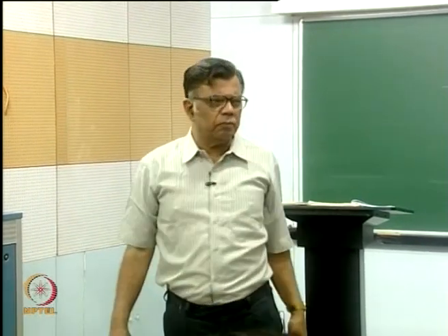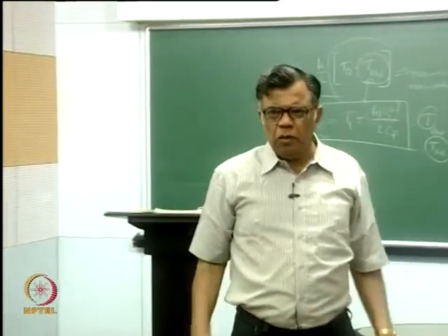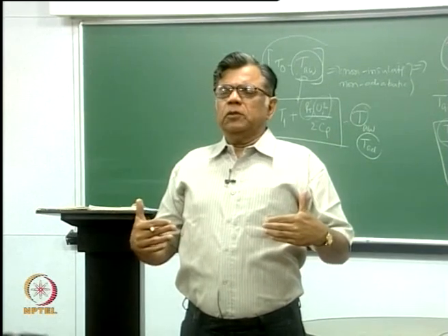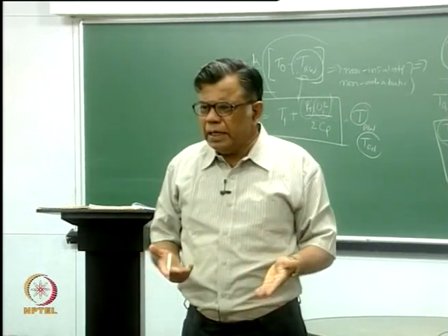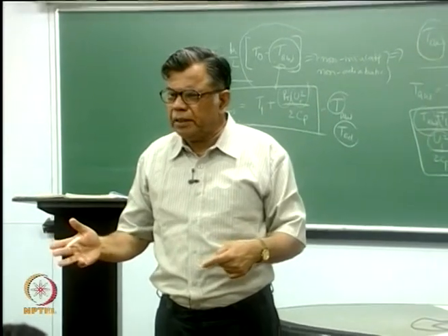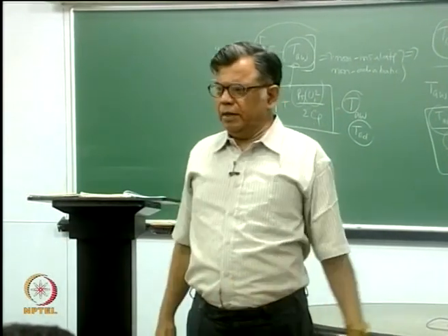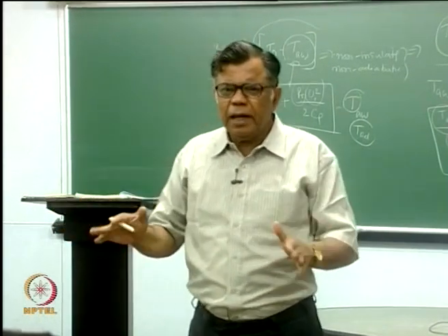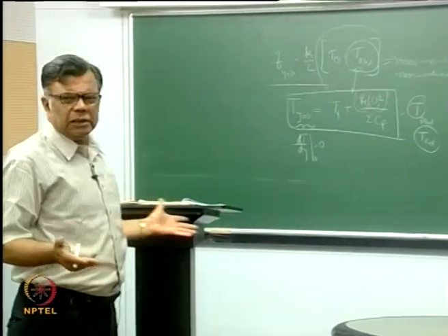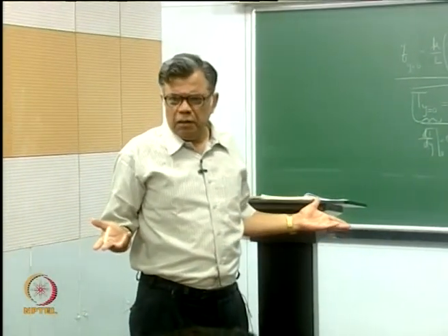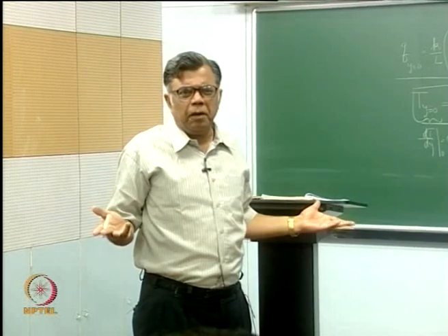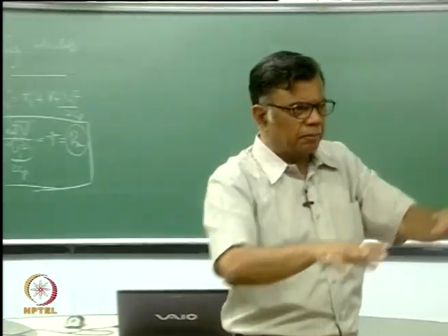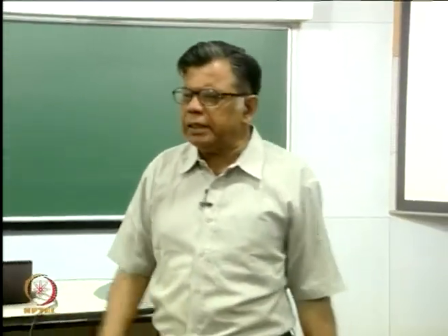Same thing in the case of laminar boundary layer flow. Usually, what is Newton's law of cooling? Q is equal to hA delta T, where delta T is T_W minus T infinity. I am saying do not do that, take T_W minus T adiabatic, you do not have to worry. Now T adiabatic has U1 squared. All it simply means is if U1 is small this is negligible, if U1 is considerable that will be important. It could be a rise of 0.001 degree centigrade when U1 is small, and you may neglect it, but it can never be 0.